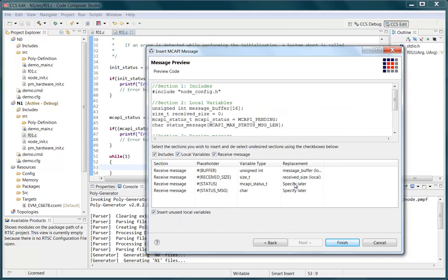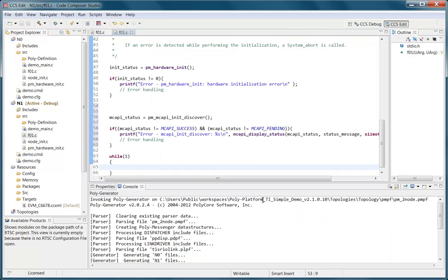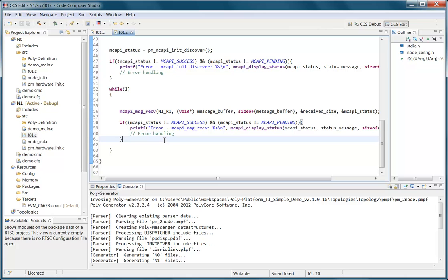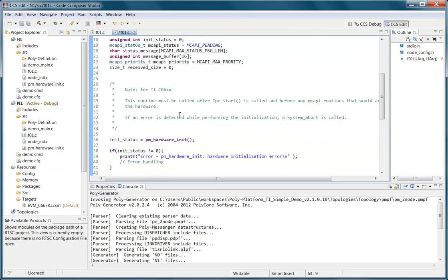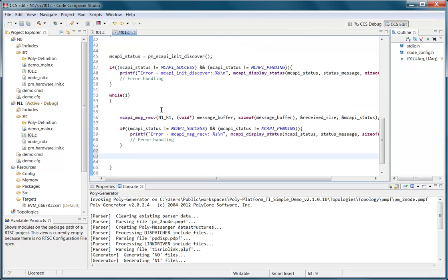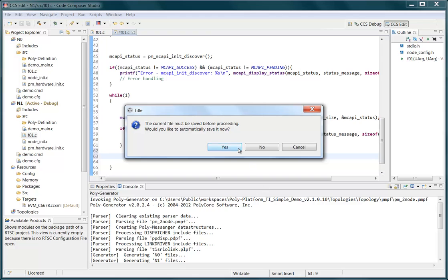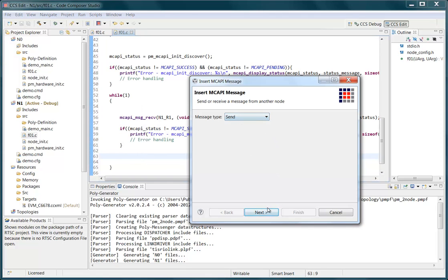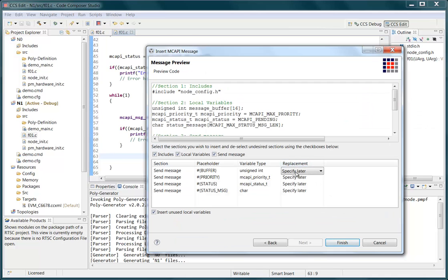There are also packet and scalar channels available in MCAPI, providing connected unidirectional channels for buffered and scalar communication. Next, we insert the message send function to send data back to Node 0, again using the template. Lastly, we set the value received to be incremented before it's sent back, so we can see the result back on Node 0. As you can see, coding using the template is pretty quick. We rarely do any MCAPI programming without using polytemplates.